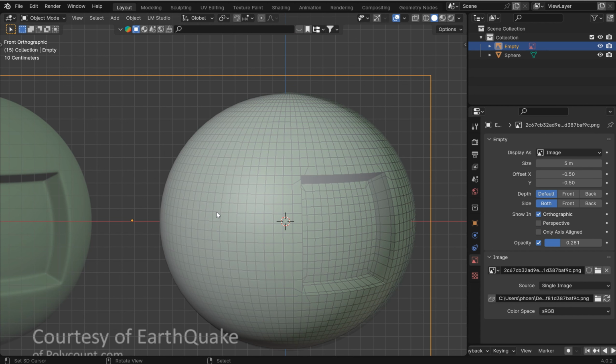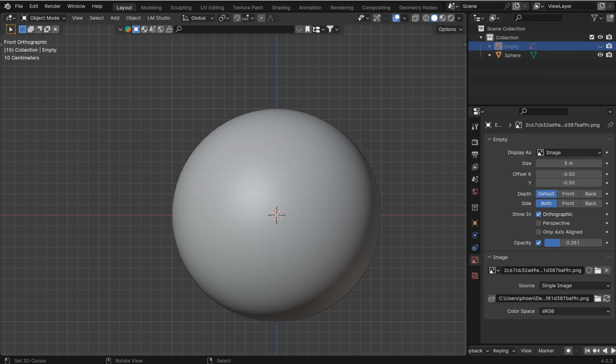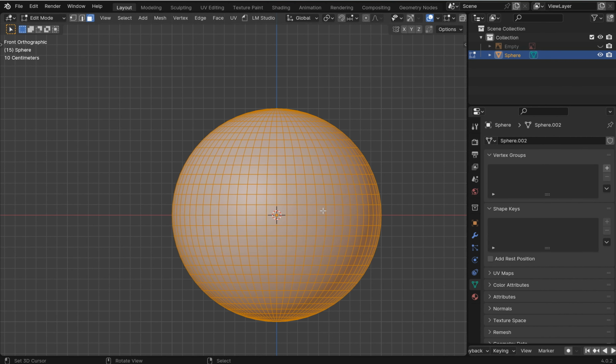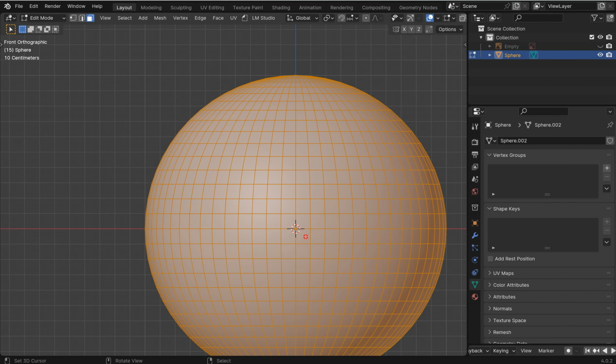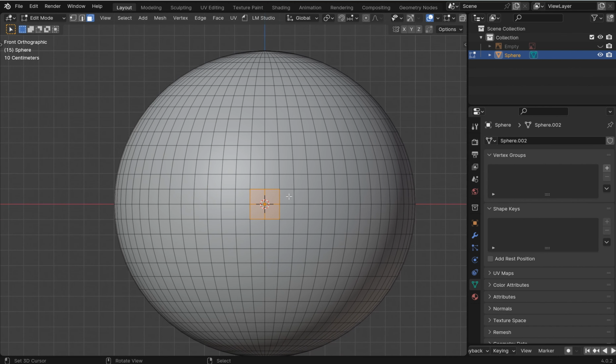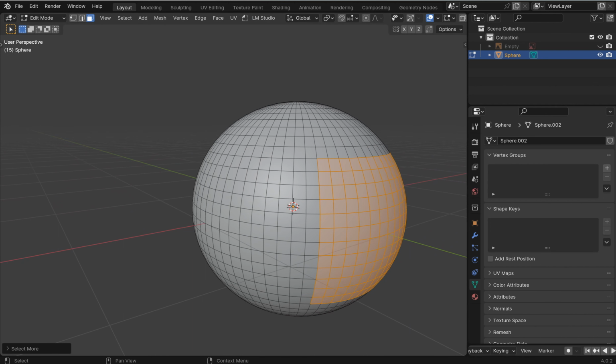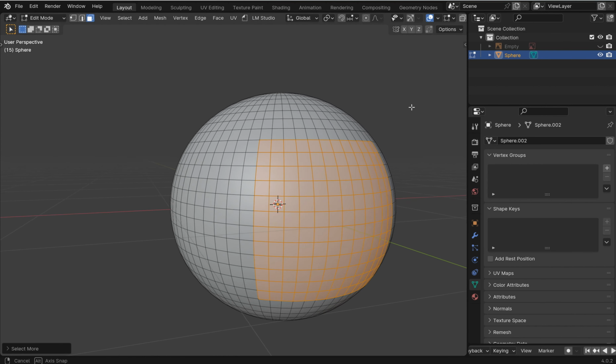Now what we can do is use its own mesh topology to kind of make this work. So I'm just going to hide this now. Alt-H will bring it back, or H will hide the reference image. I'm just going to be working from the center. And so while this is right here in the middle, I can just grab 4 of these quads, and then all I need to do is press Control plus a few times, get it to whatever size that you want it to be. Doesn't really matter.